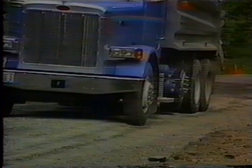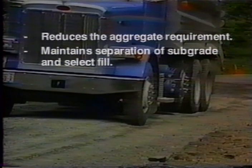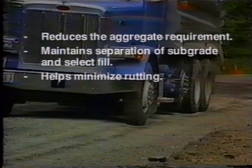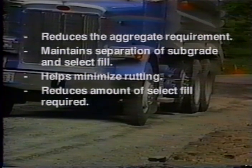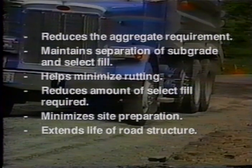A geosynthetic used in unpaved roads reduces the aggregate requirement, maintains separation of the subgrade and select fill, helps minimize rutting, reduces the amount of select fill required, minimizes site preparation, and extends the life of the road structure.